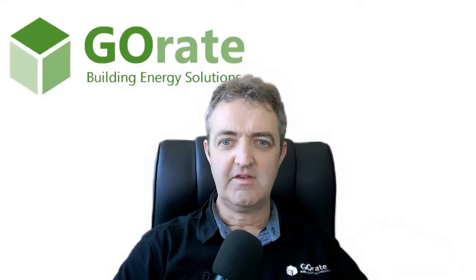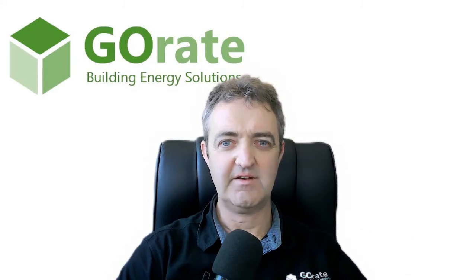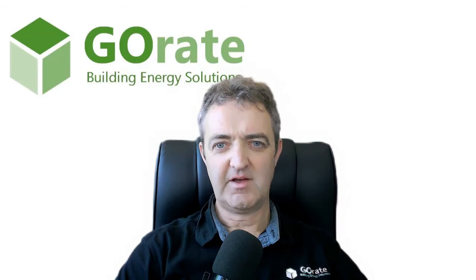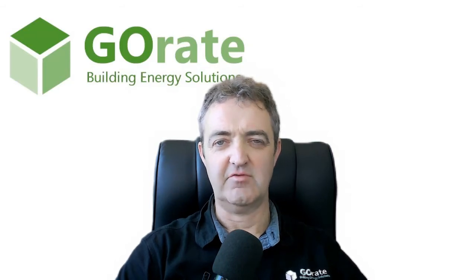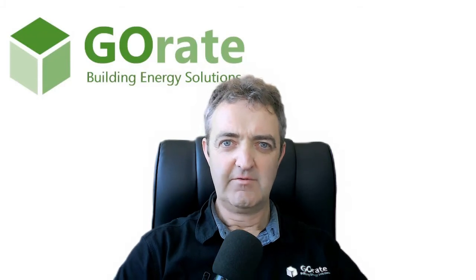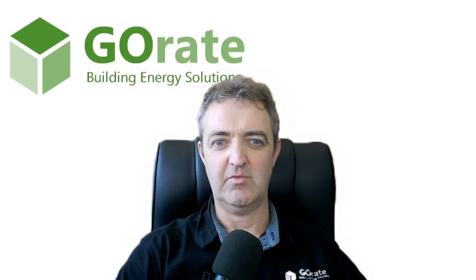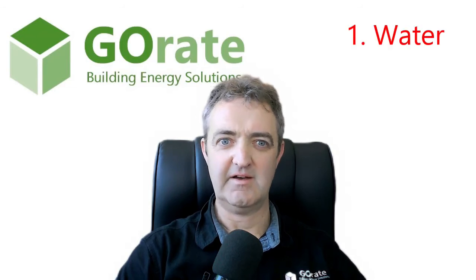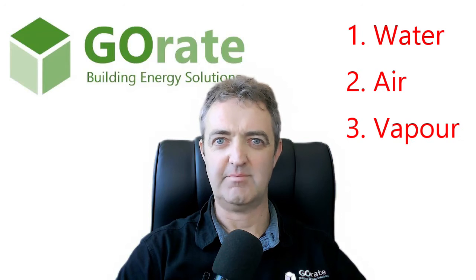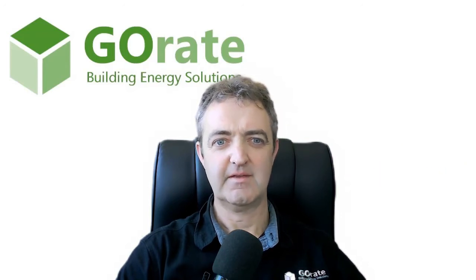It's worth pausing here to talk about what we're looking for, and it's worth taking one step back to mention our control layers. I'll talk about these control layers in another video, but for now, it's probably worth just mentioning what they are. We have 4 control layers. In order of importance, we have number 1, the water control layer, number 2, the air control layer, number 3, the vapor control layer, and number 4, the thermal control layer.